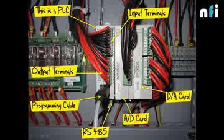Then we have the A to D card, which is analog to digital conversion, which converts analog to digital signals. Now, an analog signal can be given by some analog sensors. If you are from an instrumentation, electronics, or electrical background, you can understand there are two basic control signals, which are 0 to 10 volt and 4 to 20 milliampere. There are sensors which give these control signals. Those signals need to be processed, and to process them, we have to convert them into digital form, which makes the processing very easy. That's why we convert analog signals into digital using this card.